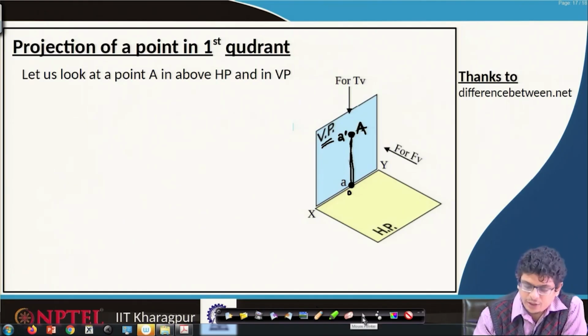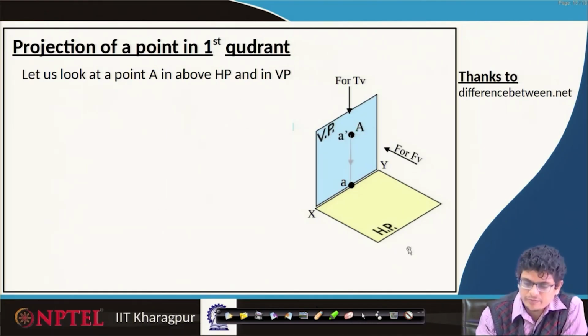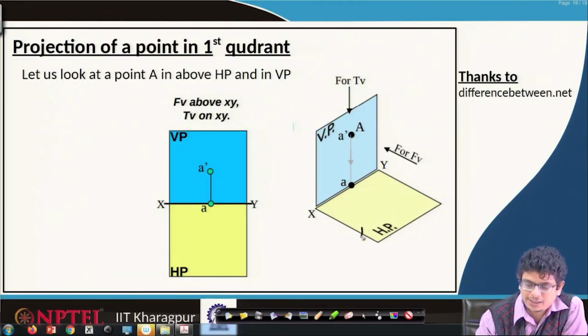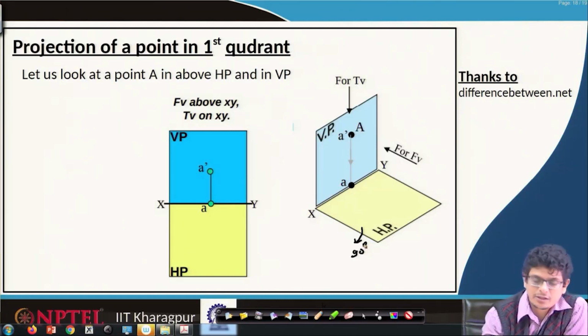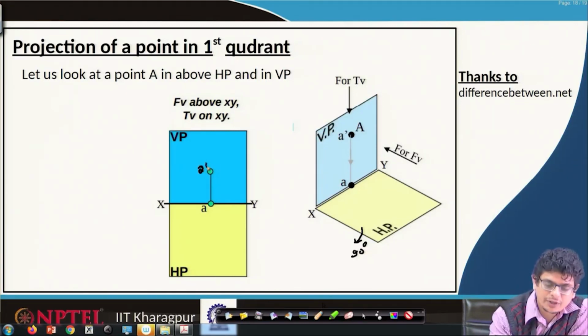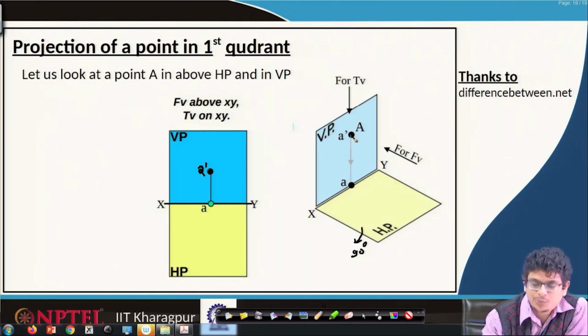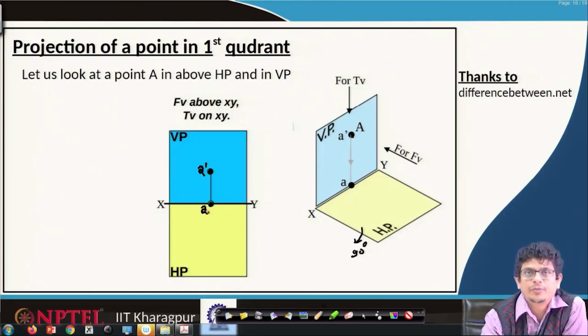That means, if we are looking at the 2-dimensional framework, where we are going to make this 90 degrees clockwise for the horizontal plane, the A dash on the vertical plane, we will see its projection, A projection on the horizontal plane, precisely maps at O. So, the projection length on the horizontal plane is 0, whereas on the vertical plane it is OA prime.